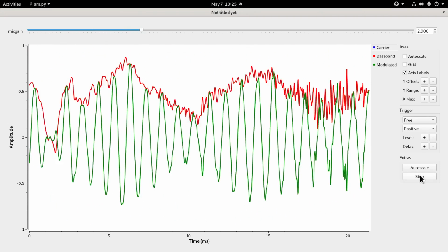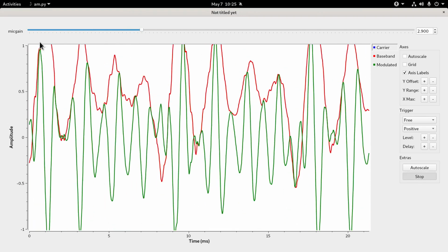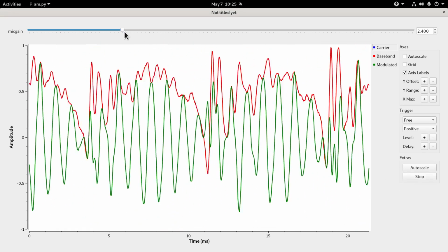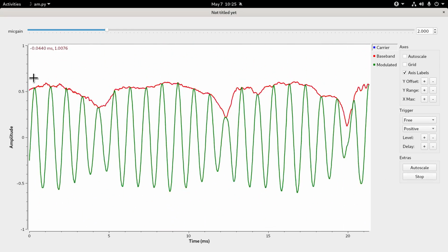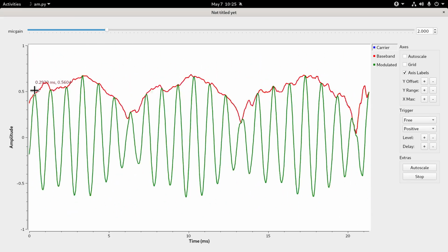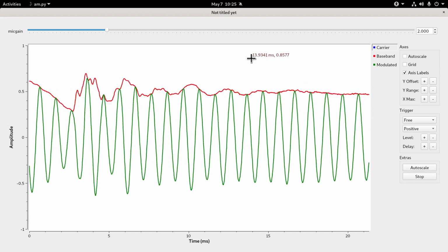Now we know though that if I go past that, if I go over, I still haven't quite made it there. So if I speak a bit louder, what's happened there is I've gone below 0, and you remember before, what happens is the modulated signal will be out of phase. I've over modulated that. So ideally, you'd have that just between 1 and 0, which would be 100% modulation. Anything less is less than 100%, anything more is over modulated.